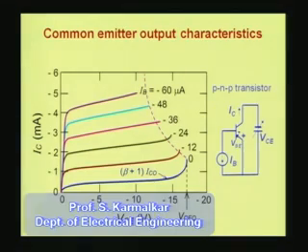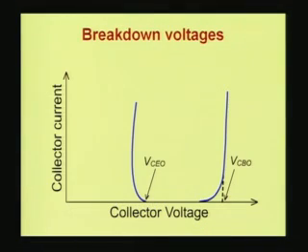In fact there are two types of breakdown. Let us look at this. Normally we come across a breakdown voltage called Vceo and a breakdown voltage called Vcbo. Now this Vcbo here is higher than Vceo. So what is Vcbo? This is collector to base breakdown with emitter open. So breakdown voltage for this condition is much higher than breakdown voltage for this condition. Let us understand why.